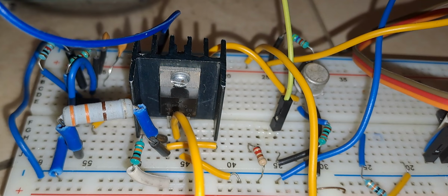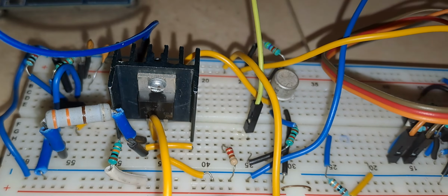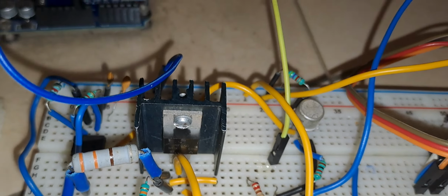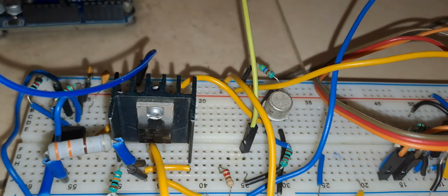So basically I have two signals, one carrier signal and one modulating signal. The modulating signal is a 50 Hz signal. I am multiplying the 50 Hz signal with the carrier signal. Presently here, as you can see, this is my oscillator generating a 48 kHz signal. This is the carrier signal generator, and here is the 50 Hz modulating signal generator.